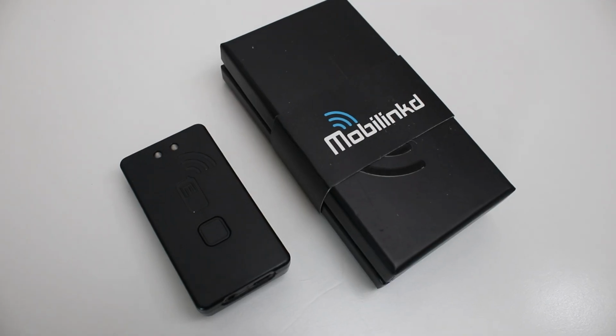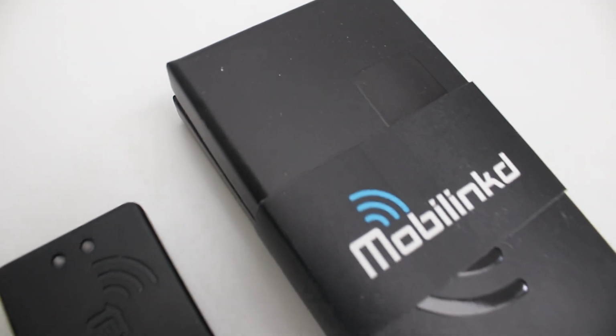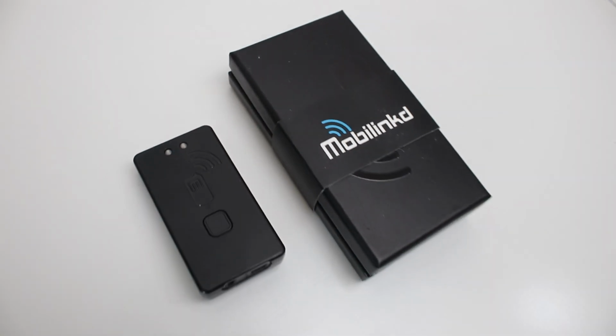to transmit. So the big difference between these two is that the Digirig just passes on the audio to your computer for later processing, but the Mobilinkd actually does the processing on board, and it's sending the packets as data directly to your device instead of the audio. Therefore, the Mobilinkd can only be used with modes that take AX.25 packets, like APRS and Packet Winlink. While that may sound like the Digirig is a better choice, that is not always the case.